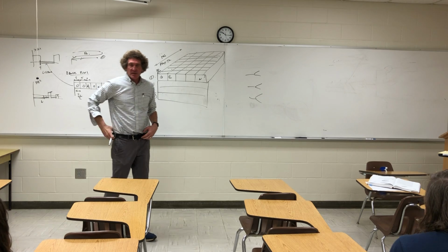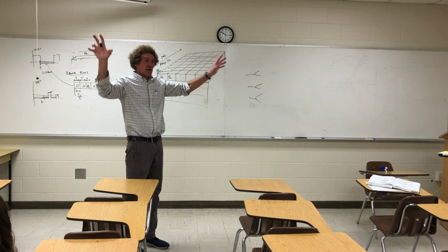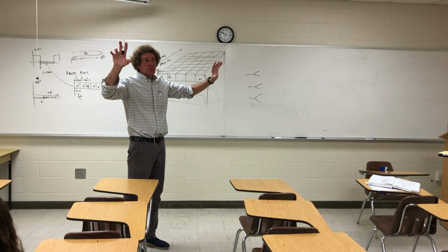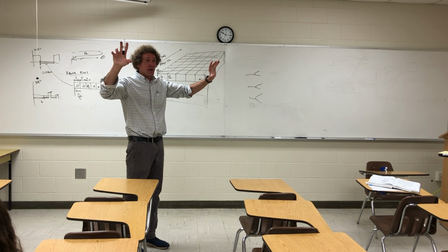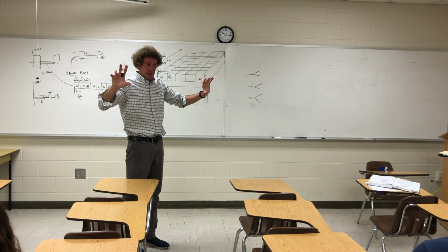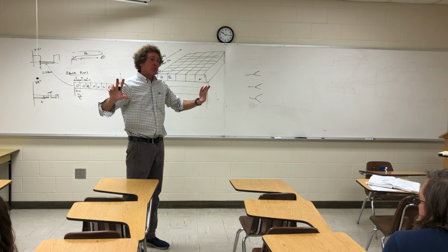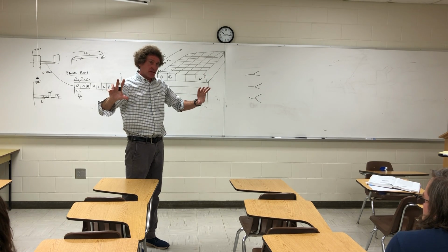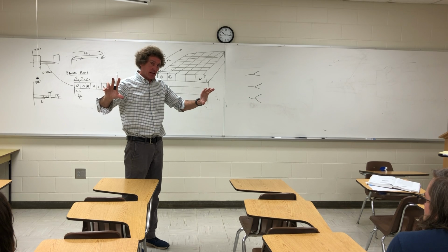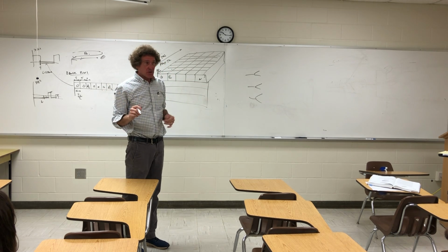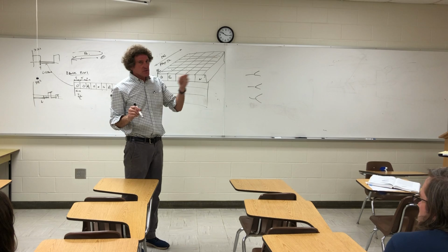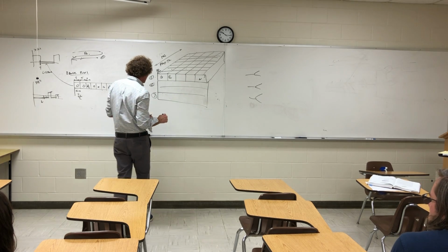Now, in the book, he talks about this. Typically, when you have antenna arrays, you have subarrays, and you will do what's called the sum of the 2 subarrays and the difference in the 2 subarrays listing. And then you're going to have something where there could be either a multiplication of the 2 or quadrature, effective real and imaginary part added together to see if there is a target or not. This is more of the signal processing that's downfield, but just be aware of that.